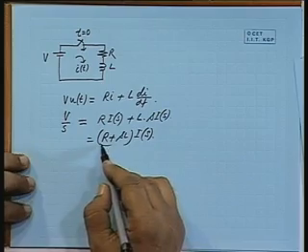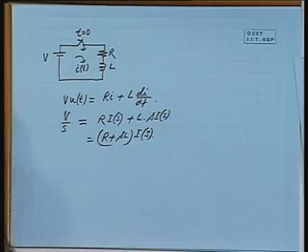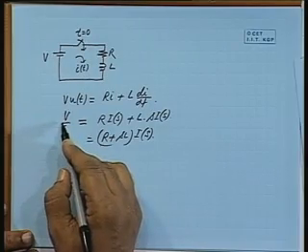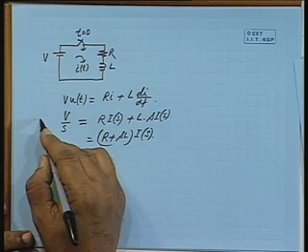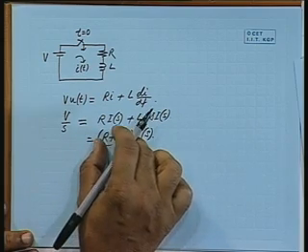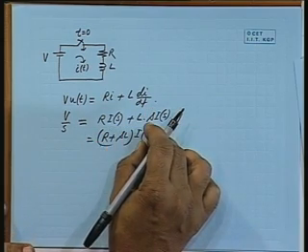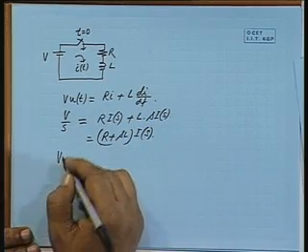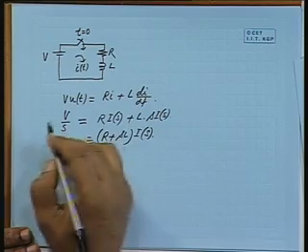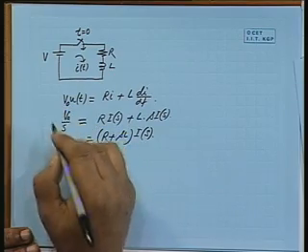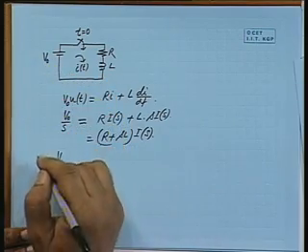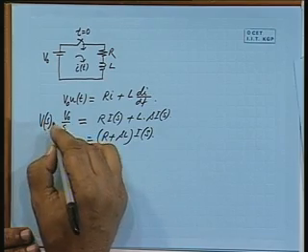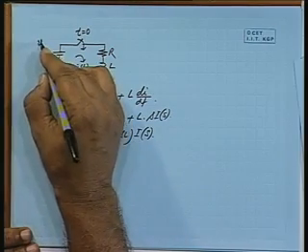Alright. So, like you have voltage equal to impedance into current in a simple AC circuit, here also the applied voltage in the transform domain is equal to R plus sL into current in the Laplace domain. I will write V naught, meaning a specific value, and V(s) is the Laplace transform of v(t).